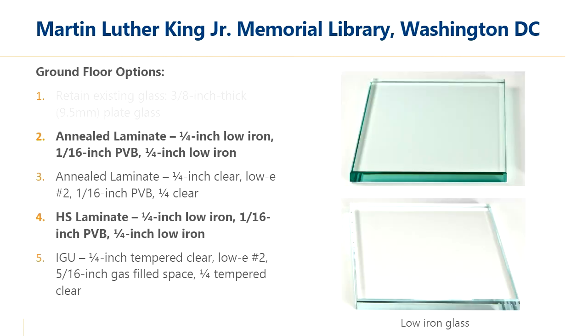So once that was figured out, a mixture of laminated and heat-treated options were considered, including laminated glass with and without a neutral low-E coating and an insulating glass unit. Low iron glass, as shown in the picture here, was selected for the first floor, as that low iron content results in a higher light transmission, and the green tint of traditional glass is significantly reduced.